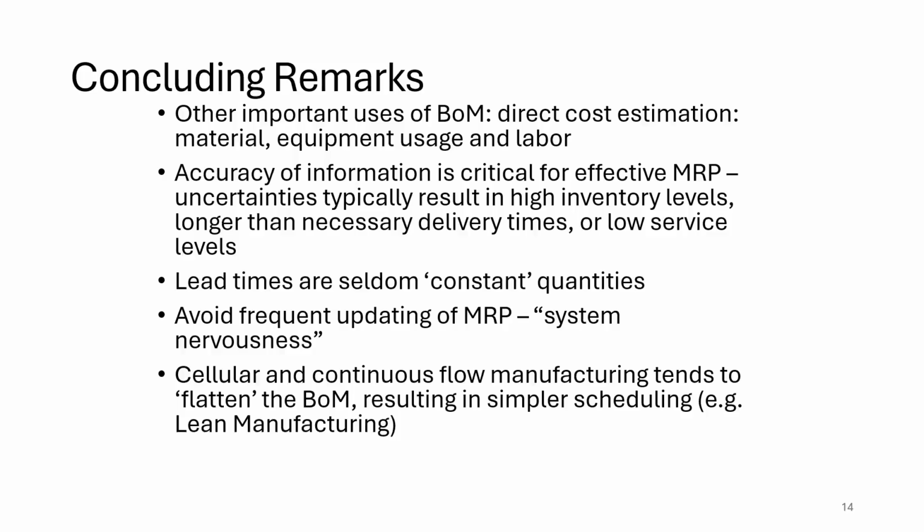So to manufacture one top level assembly, knowing the individual costs or prices of each sub-assembly or sub-part within the top level assembly will tell us the cost to manufacture one top level assembly. So that is another alternative use of a BOM, which is cost estimation.